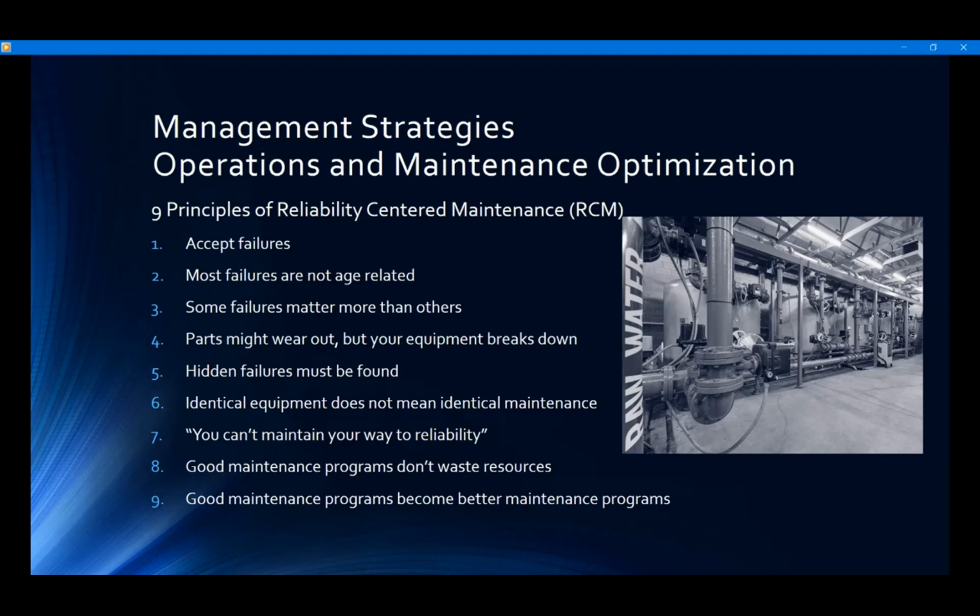First, focus on eliminating unnecessary maintenance tasks. This eliminates the direct maintenance labor and materials, but it also removes the effort required to plan, schedule, manage, and report on this work. Second, change time-based overhaul or replacement tasks into condition-based tasks. This is why it was so critical for us to get a condition scoring matrix that put everything on a level playing field for all operators.